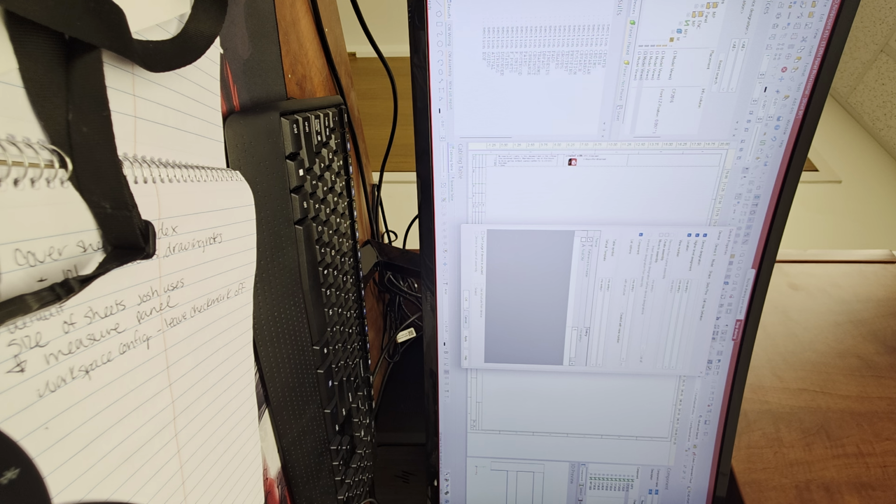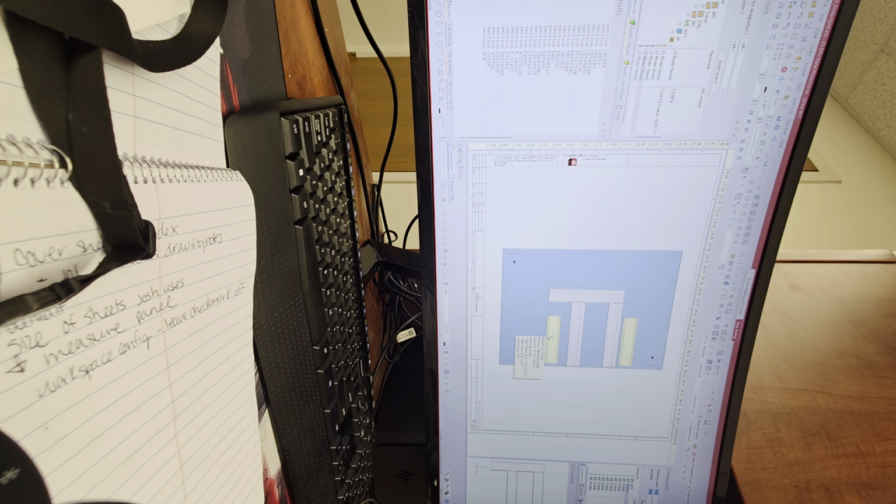Yep. All right, so if you click OK, that will do that part. Now, the second thing is you can leave these ducts here purely for troubleshooting purposes, to make sure your wires are going through, to make sure you see the links, etc. But let's say at the end of the project, just before you commit to printing, you can right click on these objects and click on symbol properties first. I think it's on symbol properties.